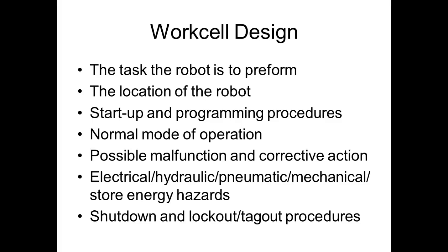The system's running, the fluid pushes it up, and then it turns off, and that big old weight up there does what? Maintains pressure in the system. This is very, very popular, because if I've got a robot out there holding something up in the air, power fails, and it loses its pressure, then what could happen? It could literally drop the load, right? So that's a very popular method.